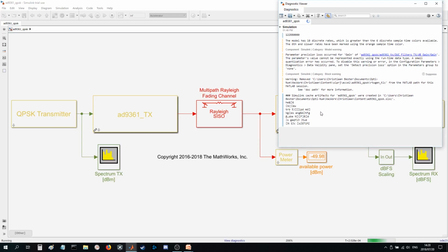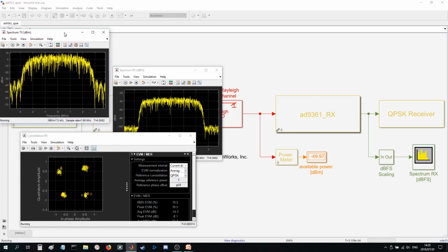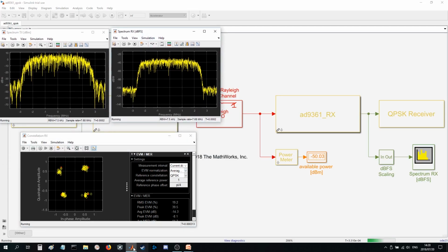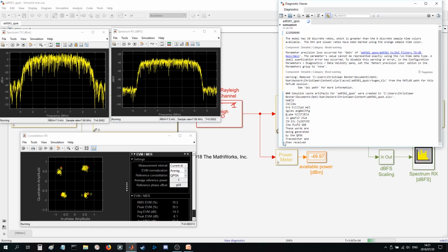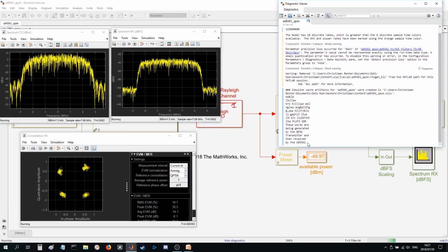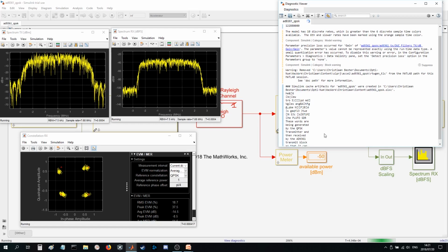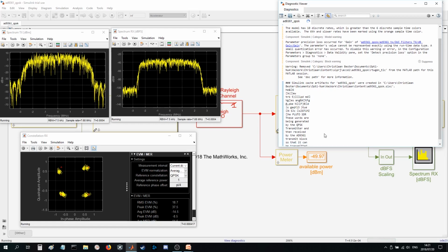The first few strings are being received as garbage since the data is still unstable. We can also inspect our constellation diagram, our transmit spectrum, as well as our receive spectrum. And here we can see messages being received block for block. Note that the simulation is application specific. However, you can use your own transmission channel and transceiver models to test the system you want to develop.